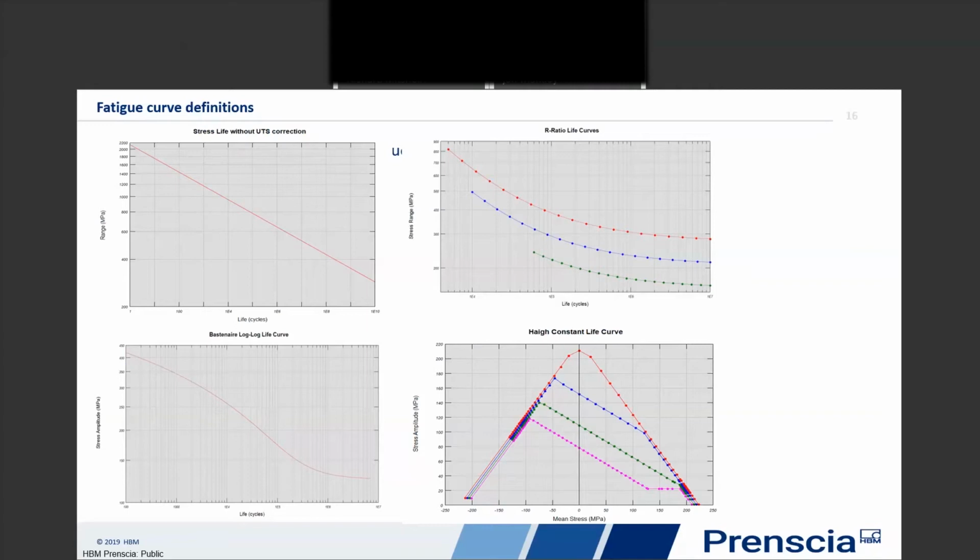Down below, we actually have taken a totally different track to describe the cycles, where above the vertical axis was the stress cycle size, and the horizontal axis was the number of cycles to a predicted failure. The bottom curve here is actually the horizontal and vertical axis are a stress state. So the horizontal axis is the mean stress of the cycle.